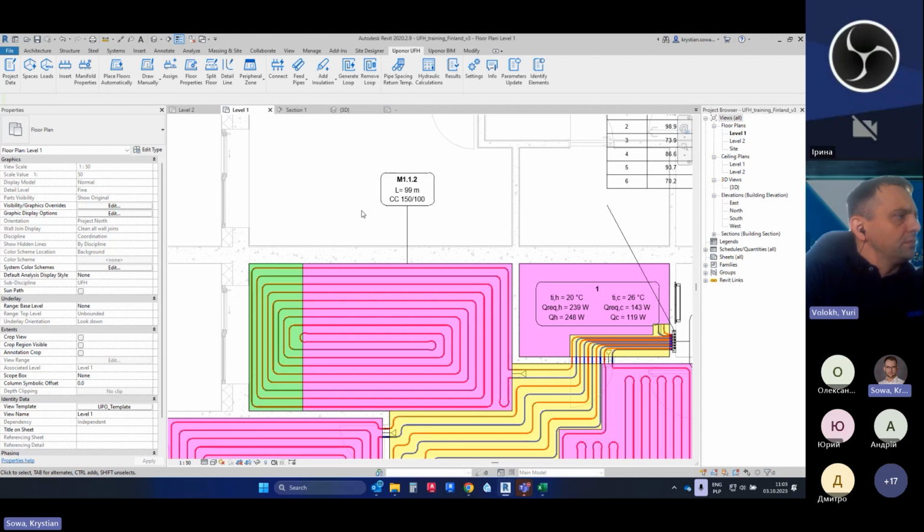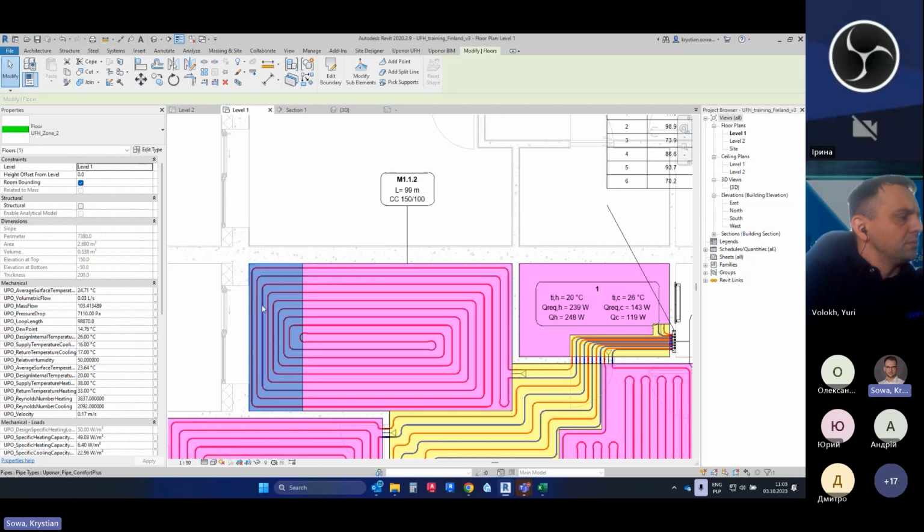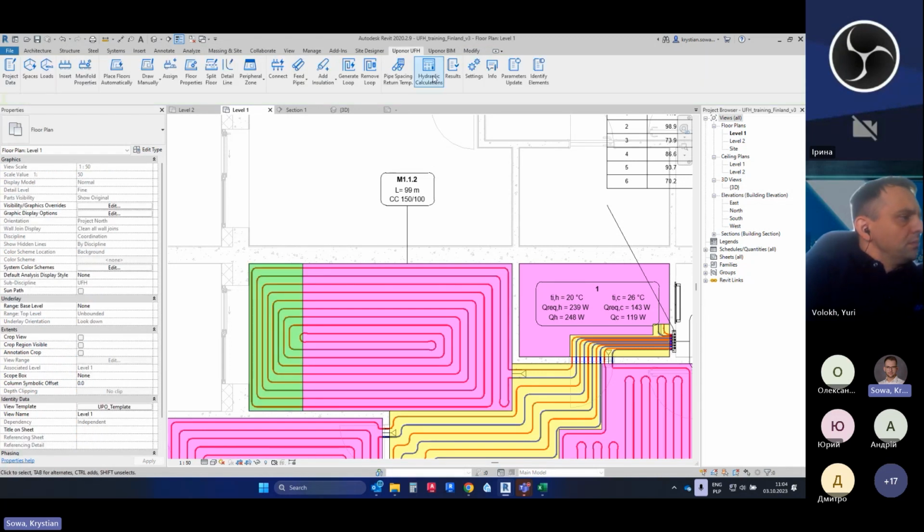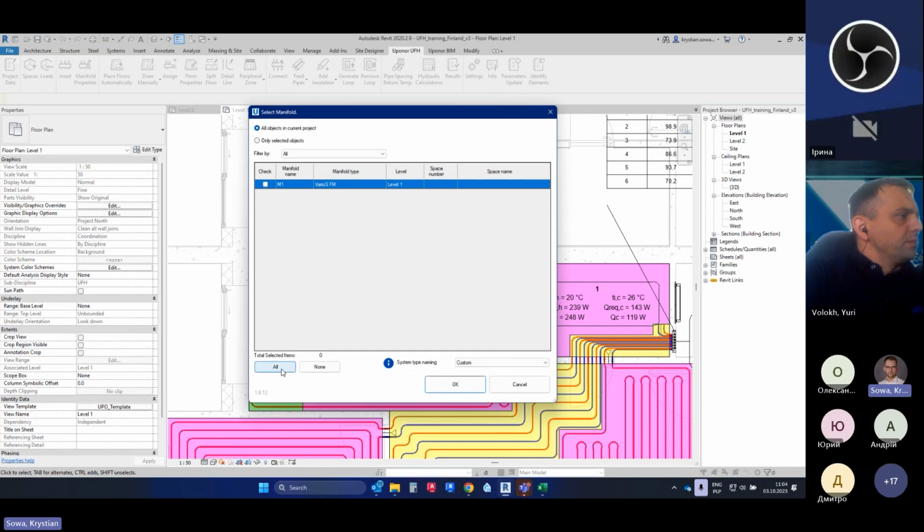And if there's 24 degrees as a design temperature, so for example in the bathroom, then there's 33 degrees Celsius. And I think, if I'm not mistaken, in the peripheral zone, it's up to 35 degrees Celsius, right? Because in the peripheral zone, you can go a bit higher with this temperature.